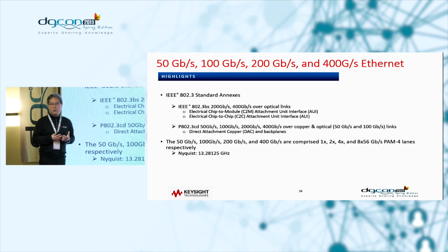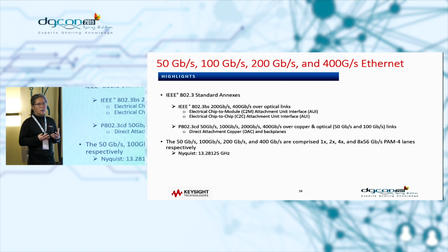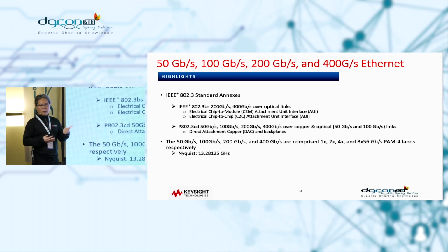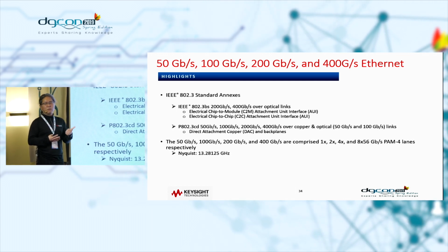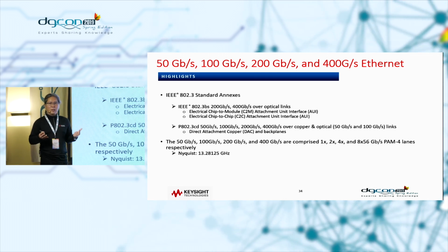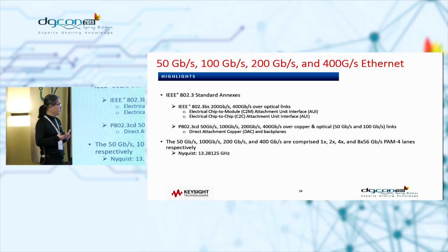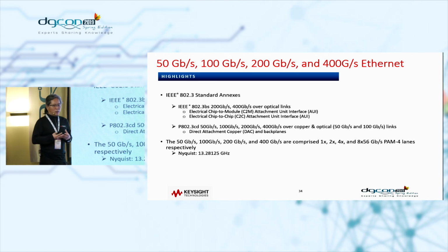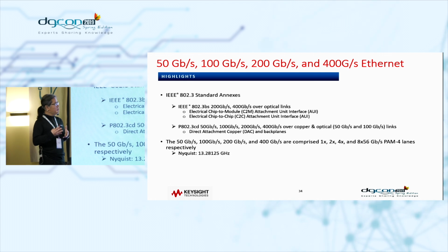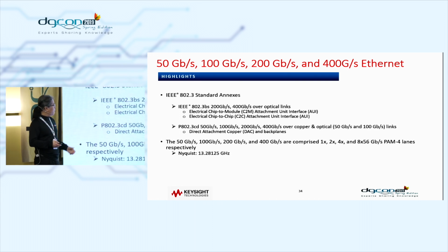like a channel sim. You will be able to get really accurate simulation data because you have a good IBIS AMI model for your transmitter and receiver, and you have good channel data, then nothing to worry about, because that's the way to guarantee your simulation for the design to be matched with the measured data as close as possible. So there are a lot of different annexes.